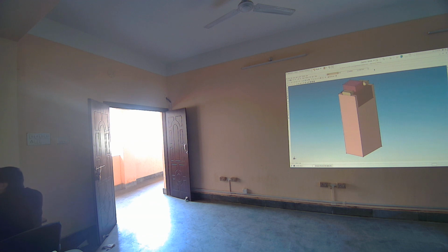Now we delete these two metal boxes in such a way that they will leave the imprint on this particular silicon block. In this way, we will get two areas marked with drain and source. Right? So this is how we are using this method to mark those two areas. So now we want to delete the complete metal area. So ultimately we don't need to select the space this time. Ultimately we have to select the body right now.